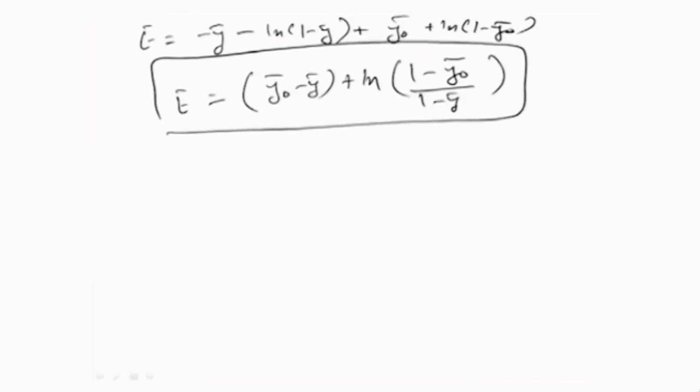So that's how the time ratio can be expressed in terms of the length ratio, where the length ratio is with respect to the equilibrium gap ye, and the time ratio is with respect to the amount of time needed by a tool going through a feed f with respect to the workpiece to cover that equilibrium gap ye.